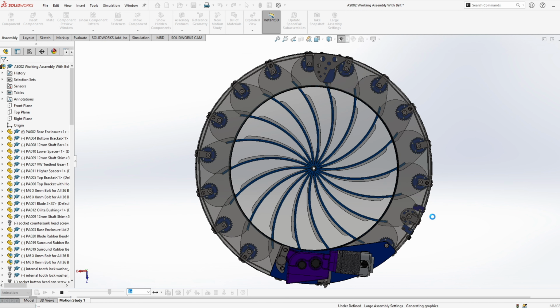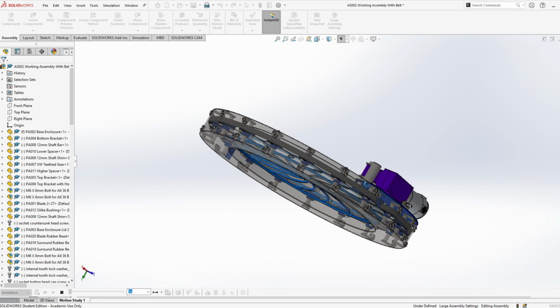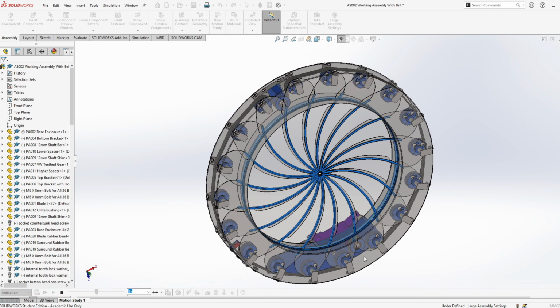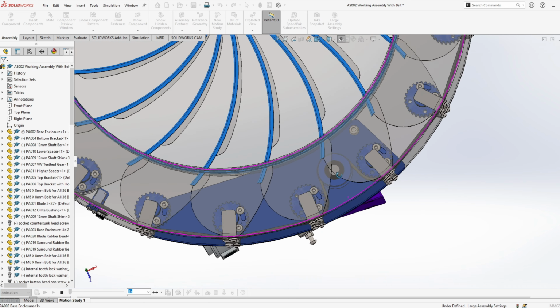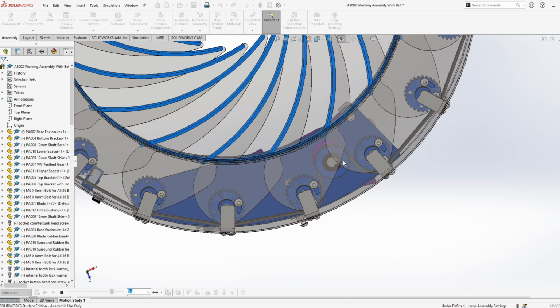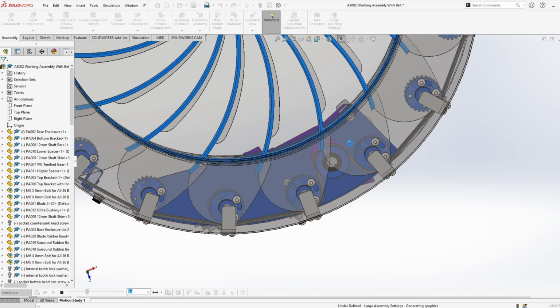First things first, I'm going to go back to the comment I made about the gearbox, how it pivots and how it adjusts the belt. If I zoom in to this point, we can see that the gearbox shaft and gear go in between 2 of the gears to tension the actual belt of the diaphragm, the aperture.